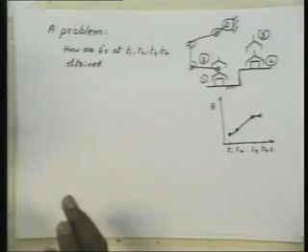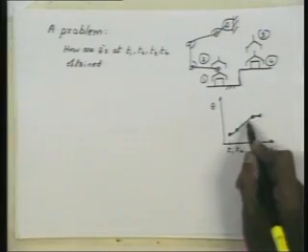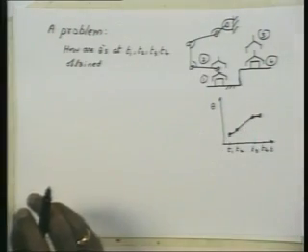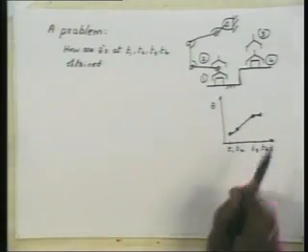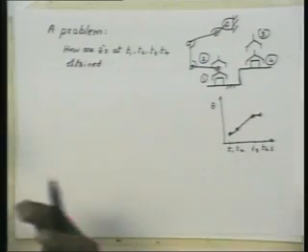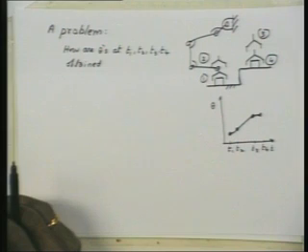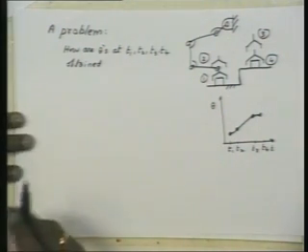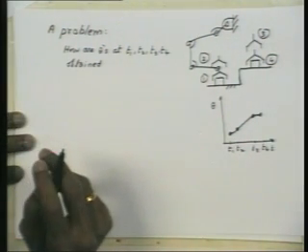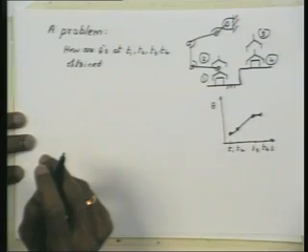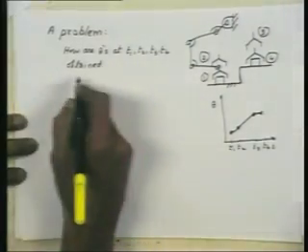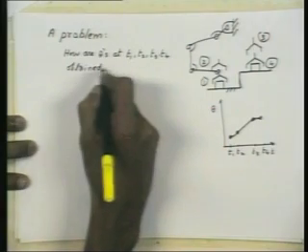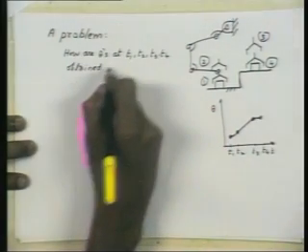So one problem is, you will realize that in order to calculate the entire path or entire trajectory of each of the thetas, you need the thetas at least at these points. Only after that can you do this joint interpolation. Fine. So this particular problem is called inverse kinematics, or the inverse position problem.